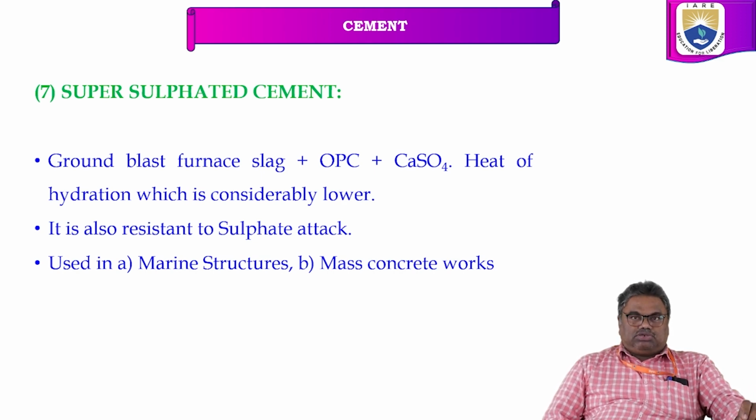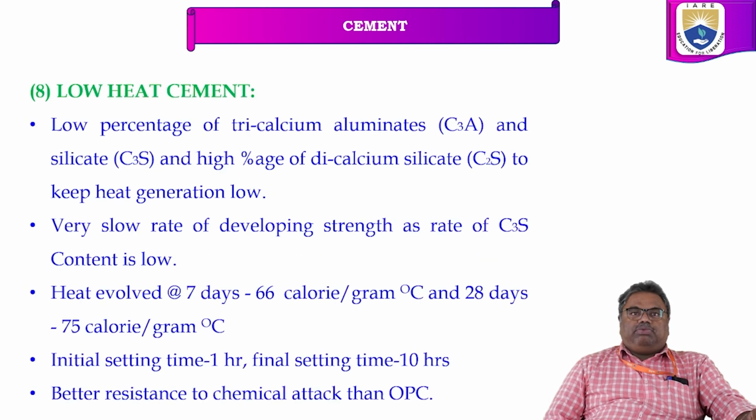So heat of hydration is considerably very low. So heat of hydration will be low in case of super sulfated cement. It also resists the sulfate attack. So this we can also use in marine structures. When you are going to build a marine structure, we can use this. And in mass concreting works, we can use this super sulfated cement.